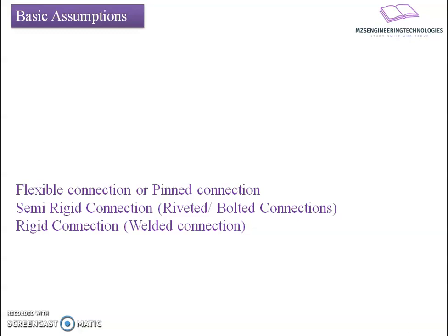In case of rigid connection, this connection will completely clamp down the translation and rotational degrees of freedom for the structure, thereby introducing additional stresses over the member. There may be axial stresses, shear stresses, twisting stresses, or we can say bending stresses developed due to twist, or flexural stresses developed due to the flexural forces.